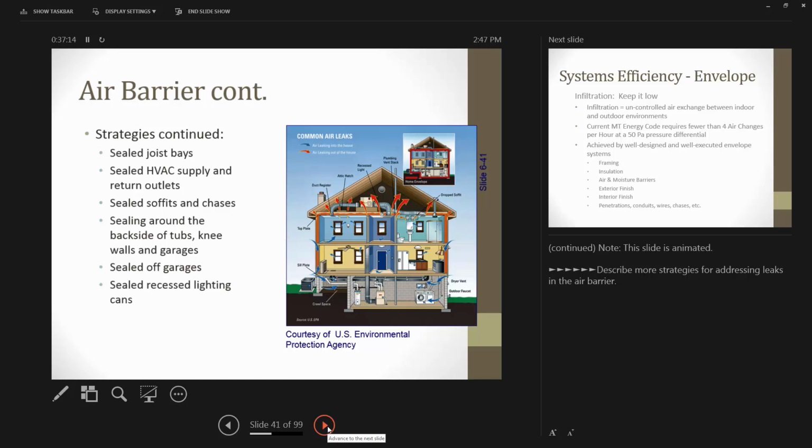That's another one I've seen in some older homes that have had some work done on them over the years. One in particular, a homeowner was very proud of themselves because they had taken a 4-inch space where they had 3.5 inches for cavity insulation, and they had managed to shove 3 layers of fiberglass into that area.